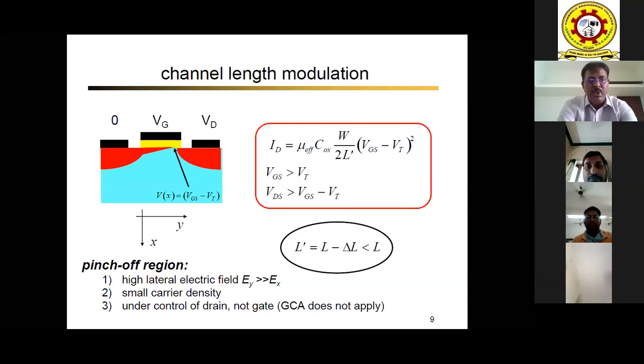So now the voltage level at the drain is the main cause for the punch through or pinch off region moving closer and closer, right? Thereby your channel length is further reduced. A high voltage at the drain makes your pinch off penetrate deeper into the gate, thereby reducing the length of the gate and reducing threshold voltage. Meaning to say, we do not have a predetermined control of the threshold voltage because of the high voltage at the drain.